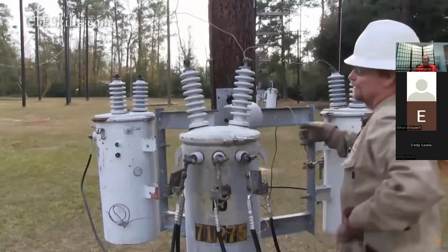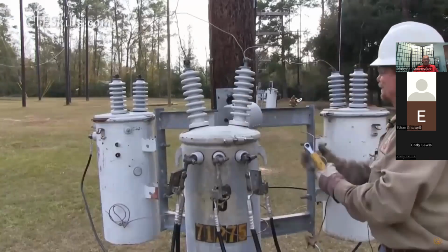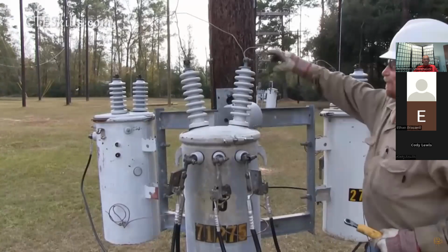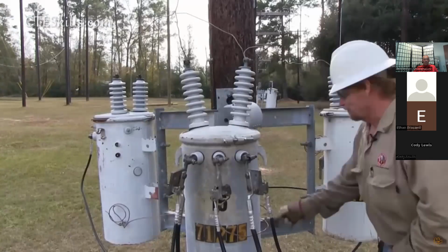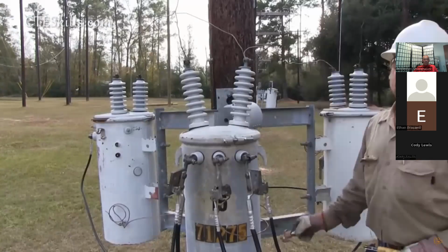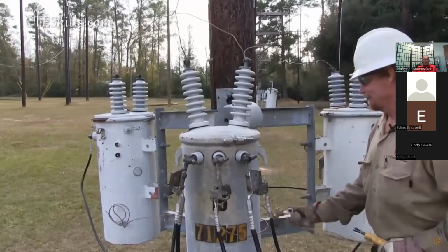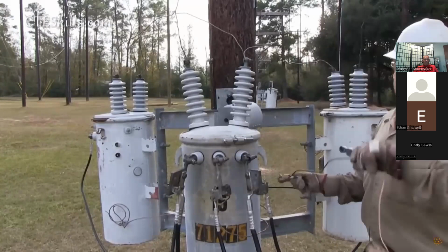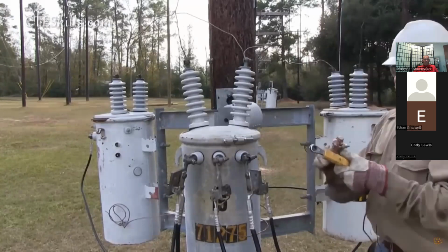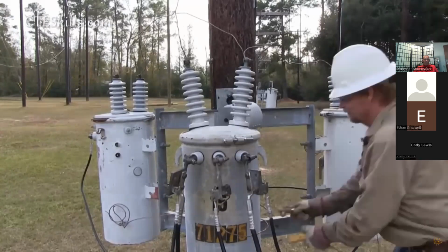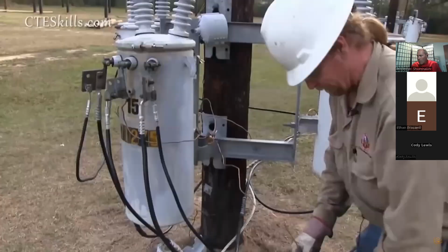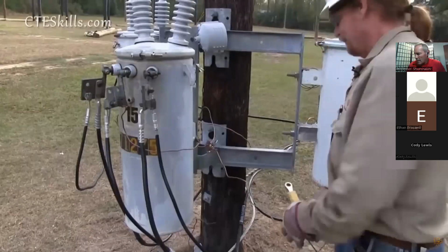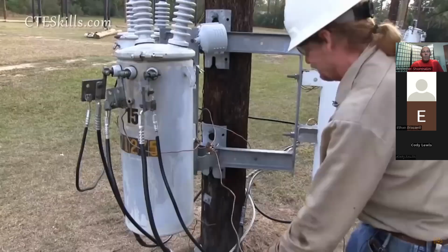There's a real simple way to fix ferro resonance. What we do is, this floater is a common point between transformers, but it's not grounded. That's what makes it float. But in order to fix that, we attach a small ground, just a temporary ground, and we can connect on these. What I'd normally do working on this in the field is take an insulated stick and attach this ground here.